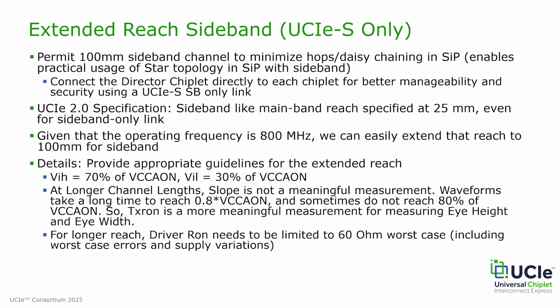Now with UCIe 3.0, what we are doing is extending that sideband channel. Instead of forming a ring, if somebody wants, we can support a star topology. With the star topology, you can minimize the hops because the director chiplet or the anchor chiplet is connected to every other chiplet.